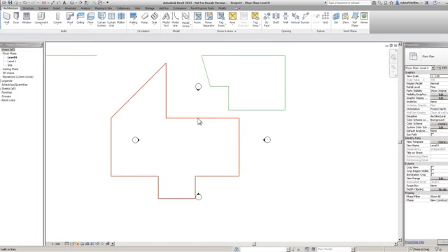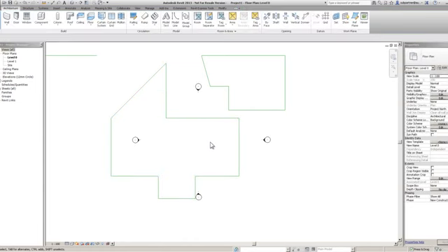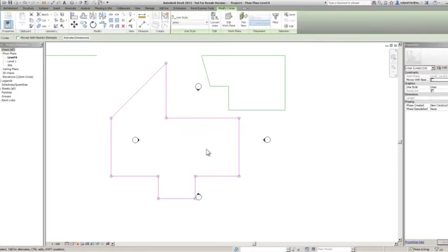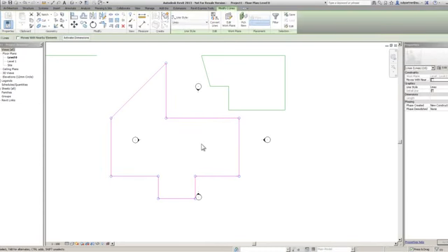If I just left click now, it's going to select all the lines or elements within that chain. I'm just going to unselect them by clicking in a space. Now, just a little mistake people make: they quite often hover over it, hit tab, then move their mouse. Because it's only a soft select, a temporary selection, if you move your mouse off it, it's going to drop that. So just have a little practice of it. Hover over it, hit tab, left click. Again, hover over it, hit tab, left click. Fantastic. So that's another way of selecting things.